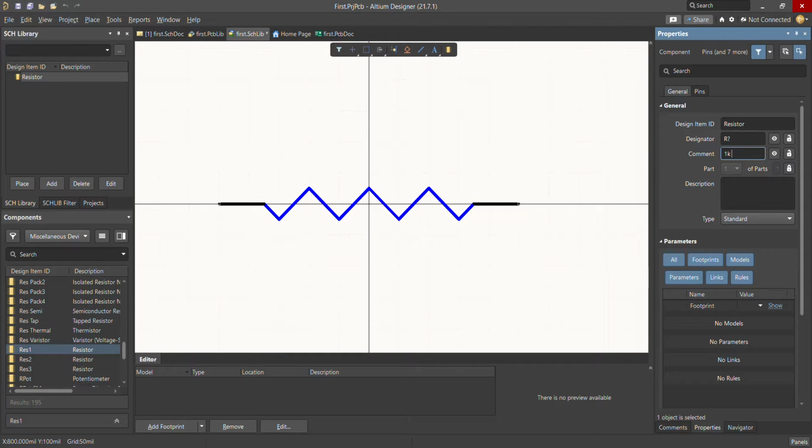And then the size of the resistor. These are things that the manufacturer tells you on the website that you're buying from. But let's say for now we are choosing a 1K resistor, the size of it is an 805, and all that stuff. Usually the website that you're buying from has a comment section. We would usually copy the comment section on the website and paste it down here. As for description, again, most components have a description section. So we are going to find the description on the website and copy it here. So we have the description for it.